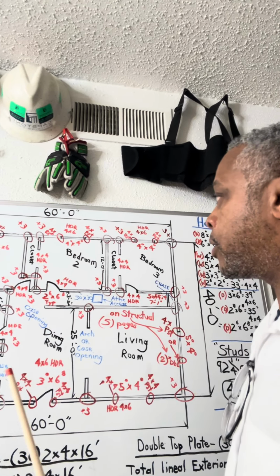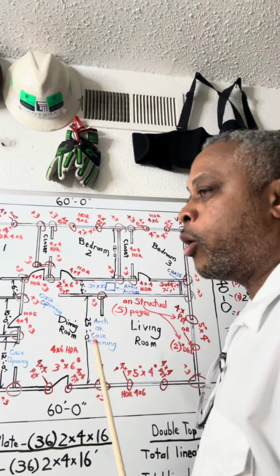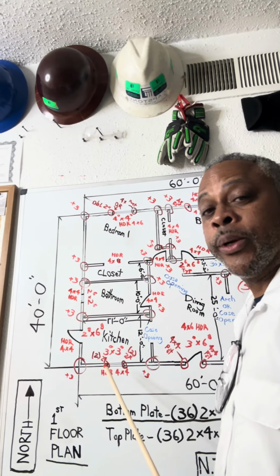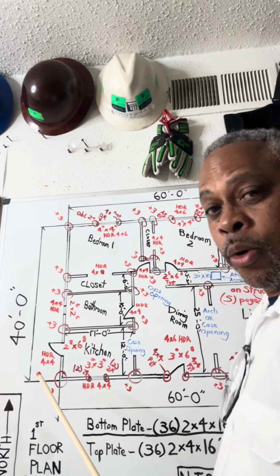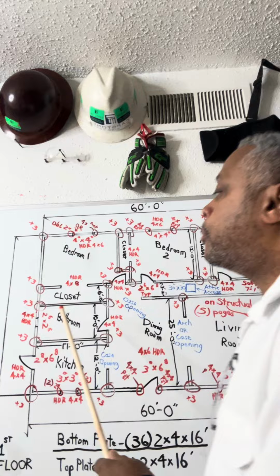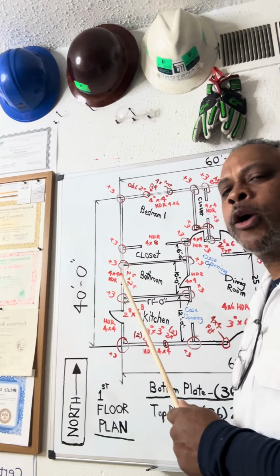Each header has a size opening: 4040, 504, 3030, 60. The kitchen is 3030. Okay, the back door is 2868. That's a header there. My bathroom window is going to be an obscured window. It means it's probably not going to open.